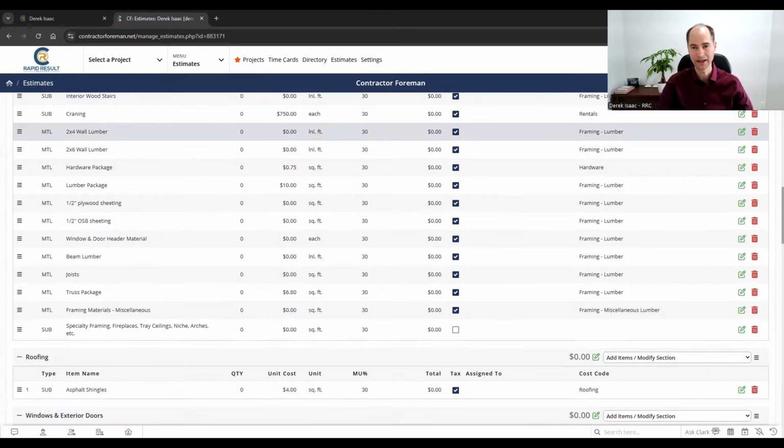And then for me, I like to do my wall lumber. When you've got digital takeoffs, you can figure out your walls, and you need to figure out your walls anyways for drywall and other measurements and baseboards. So doing a takeoff for wall lengths is helpful. You may as well get your framing takeoff lumber from it to build some accuracy instead of just doing a square footage. You can do that.